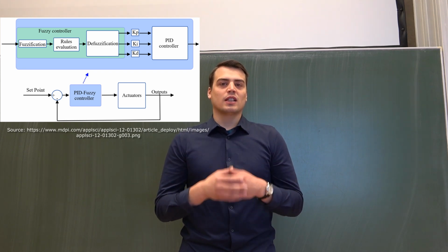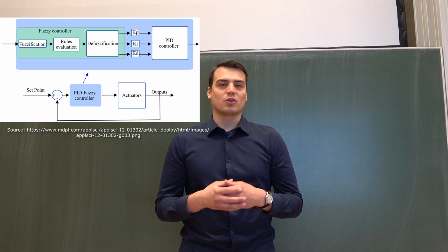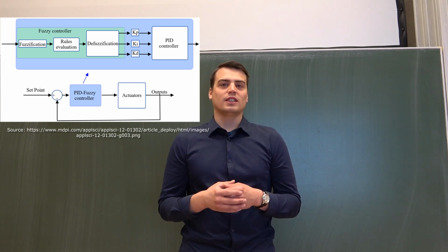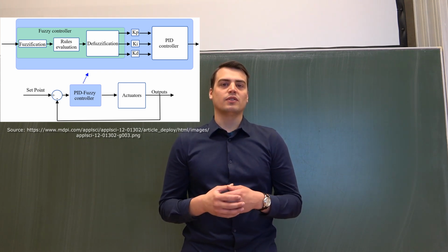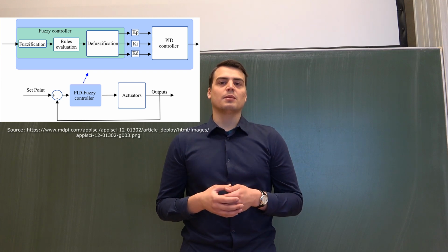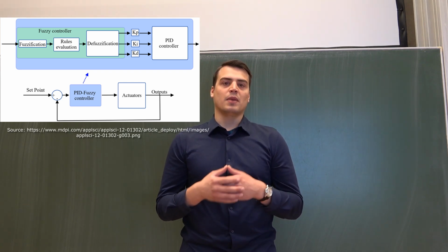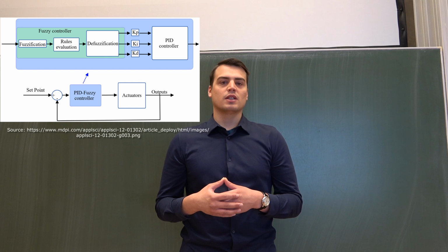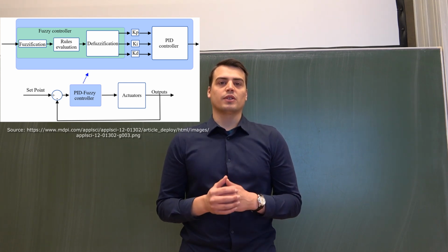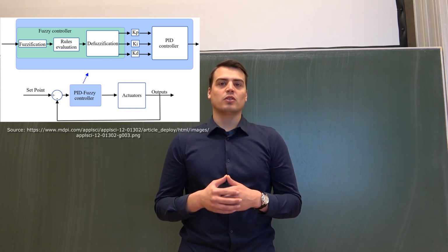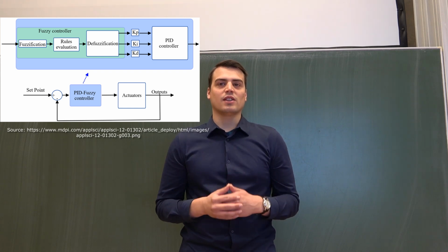This is known as a self-tuning fuzzy PD controller. In this research, FLC adjusts proportional and derivative gains based on real-time system behavior, ensuring better handling of disturbances and modeling inaccuracies. This process is called adaptive gain tuning.